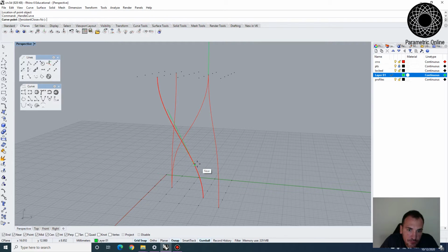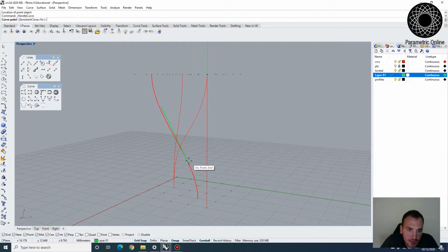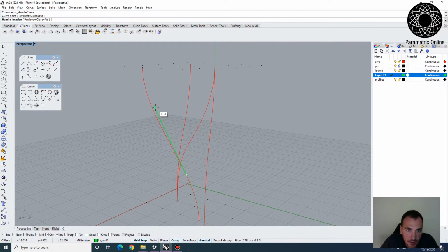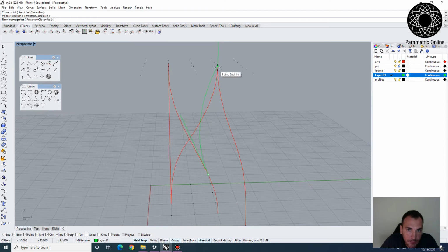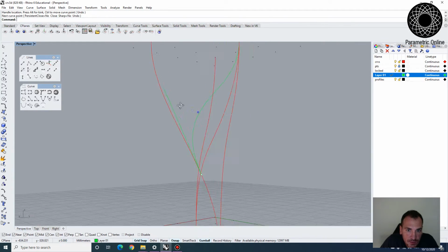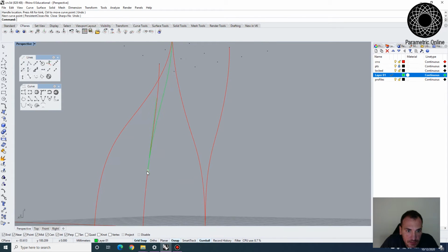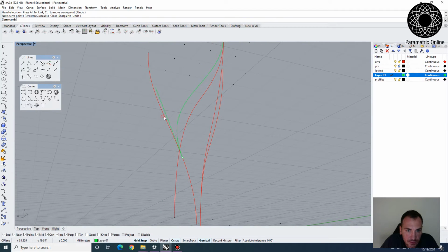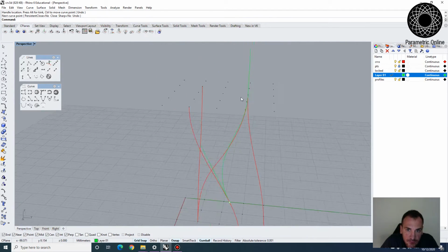With the handle curve, we select the input, and then we select the starting deviation. That starting deviation should be on this line, which is tangential to the red curve. Then I can come up here and select an endpoint and choose this vertical line. You can see that curve is now splitting off from this red line and going off to this tangent curve.